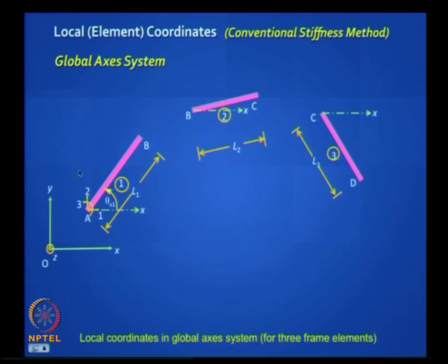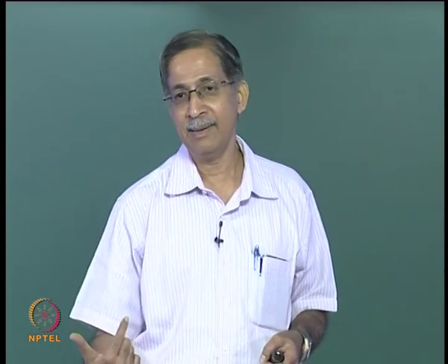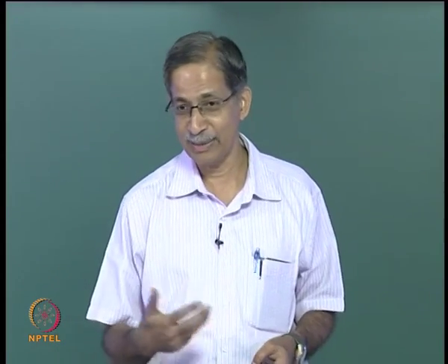So this is a big change. That means we do the transformation here itself. So I am not putting the star anymore. Remember 1 star, 2 star, 3 star, there the 1 was pointing along x star this way, 1 was along that, 2 was normal to it. Now 1 is parallel to the global x axis and 2 is parallel to the global y axis, and you will find the 3 does not change. Why does not the 3 change? Yeah, because the vector pointing outward from the xy plane is the same, so there is no transformation needed there.